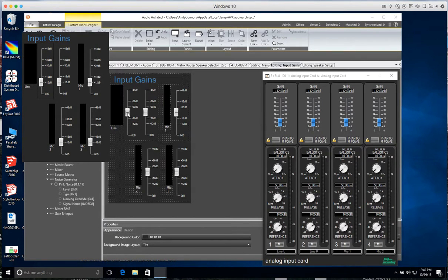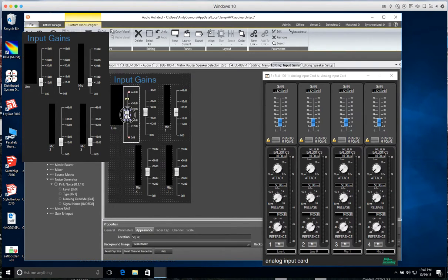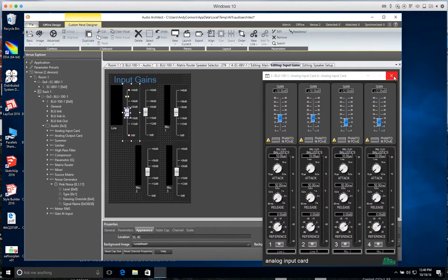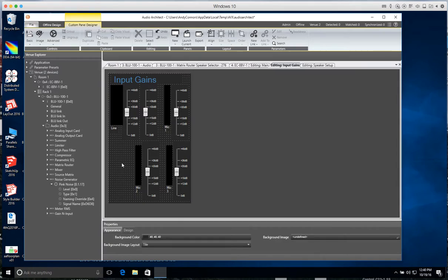run panel. So, whoops, you caught me. Run panel, here we go. So this is adjusting the input gains. And then this meter corresponds with that, so you can see how you're doing. All right, so this would be to set up your input gains just so that you know you're getting enough signal into the SoundWeb when you change things around.